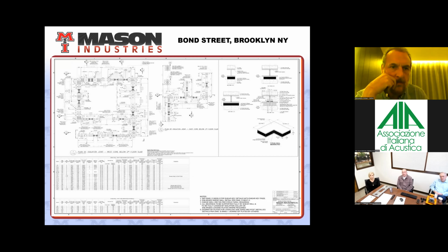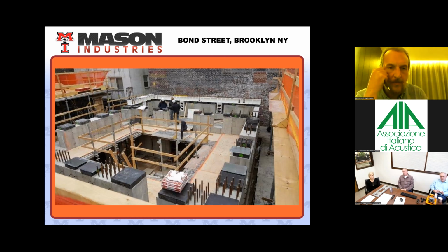We use shear keys to handle horizontal loads through the elevators, and what they actually look like in practice is this picture that shows the horizontal shear keys here, where there's no steel in place, the bearings that are supporting the load of the elevator chase. And these rods that protrude are there to prevent overturning. So there happened to be, in this case, overturning moments being generated by wind loads that were compensated for as well.